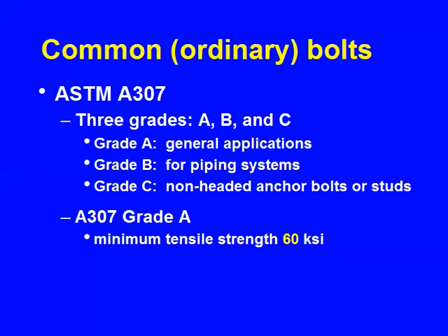We have to have a starting point, and the starting point is let's do the tensile test. Either you do it or presumably you pay someone to do it. It's an easy test to do, and it's the benchmark. Now, if the fastener is acting in some other way, which is the more common situation, most bolts, for example, operate in shear, we have to have the linkage between our acceptance test, in this case 60 KSI, and the shear strength, and I'll be developing that.